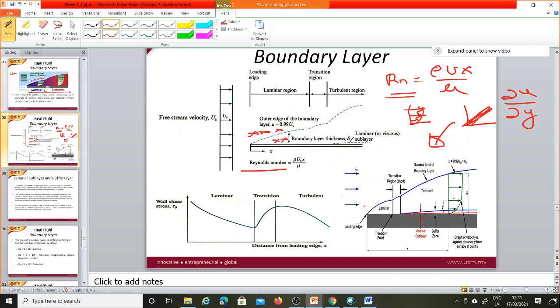These are all synonyms, and we understand what you mean by these words. So we call this linear. Within the turbulent zone we have a region where we consider the velocity change to be linear, so we call it laminar. So inside the turbulent we have the laminar sublayer. It is not a layer, it is a sublayer. And why laminar? Because we consider the velocity change to be linear, since it is very small.